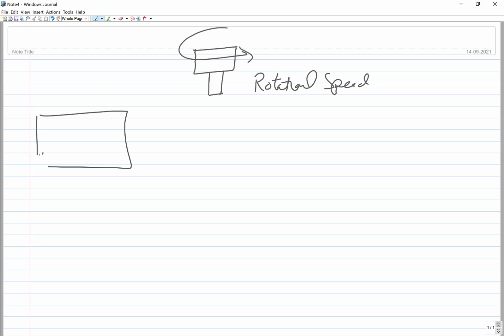Let's say this is the weld line in top view, this is the tool pin, and this is the shoulder, the tool dimensions. If you keep on rubbing at a particular location at, say, 200 rpm or 800 rpm, then when you rotate at a much higher speed, the more frictional heat generated in less time leads to a more localized rise in temperature, and the increased temperature causes more thermal softening.